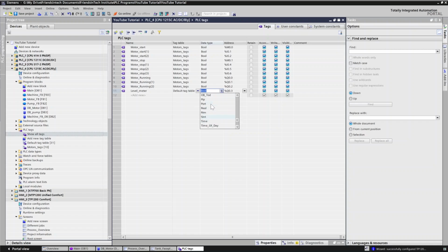Or I can use real. So you can either use int or real here. So you can just type integer. That's it. Once you have integer here, you have to change the address. The first thing you have to change is the operand identifier to I, then the address you can leave as 0 or you can change to 2. But let's just leave it at 0. That's okay.